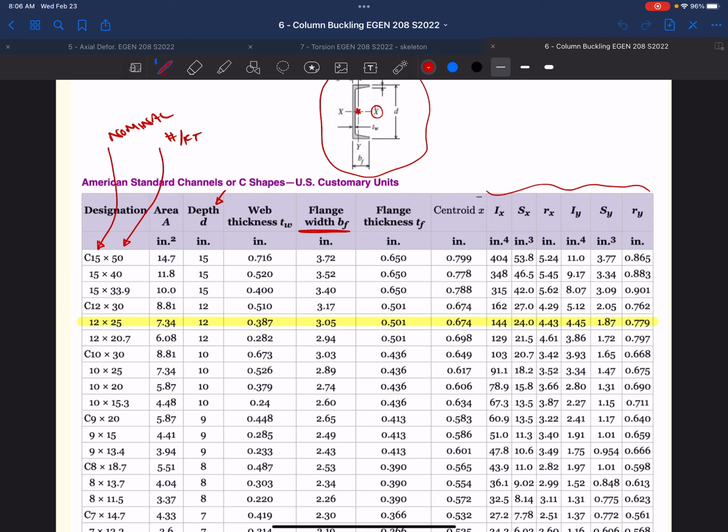And so, especially with wide flange columns or even channels, as we noticed in the example when I went through it in the lecture notes, the resistance for this section to buckle is different in one direction versus the other. If this were to buckle vertically versus buckling side to side, so this thing's sitting here, and if it wanted to buckle one way or the other versus back and forth, it's going to have a different capacity, right?